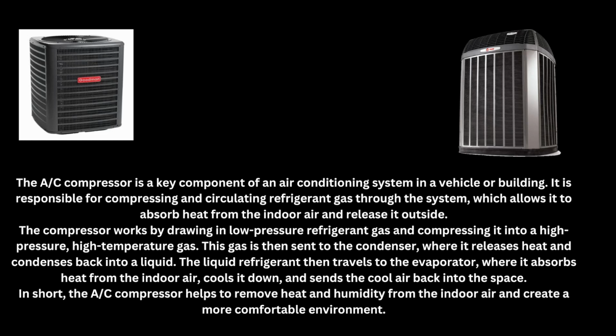It is a 220 system outdoors. That means your indoor unit can be 120 or 220, and then your outdoor is 220 volts. And it's real easy and real simple. It doesn't change unless you get into the commercial realm. There are some residential home units that are 220 three phase. Most of your residential systems are 220 single phase, and we will go over the difference between single phase and three phase. Three phase is linked towards more commercial.